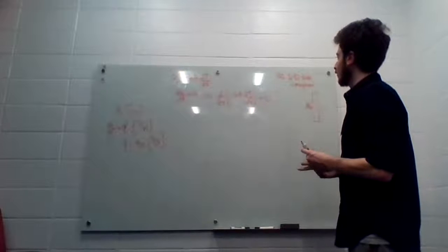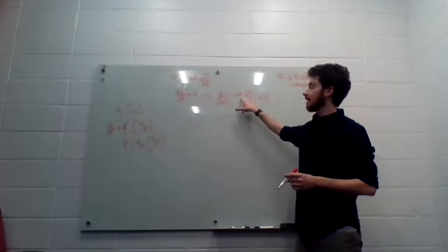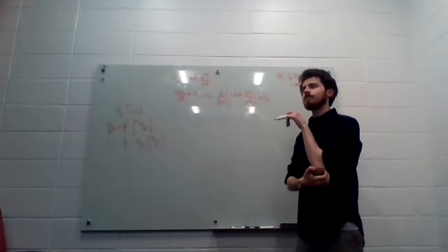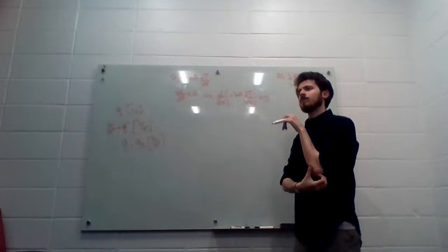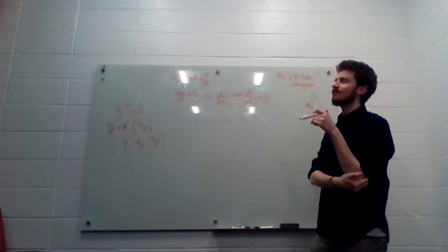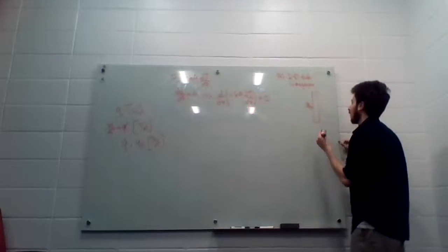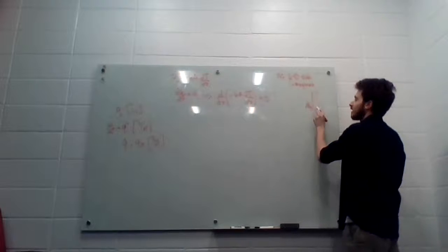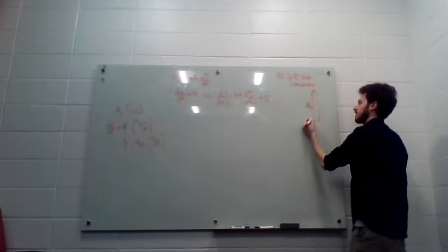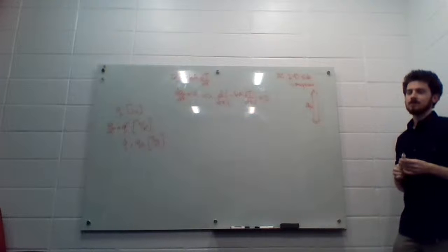Okay, so what we can do based on these two assumptions, the isotropic assumption that K doesn't change with X and the area doesn't change with X, is we can move both of these to the outside. Yes? He mentioned something about assuming that it's an infinite wall. Is that for this kind of problem, or when do we assume that? Yeah, so the reason that we assume the wall is infinite, which is a super silly assumption, is whenever you've got a finite wall, you've got corner effects. So Q right in the middle of the wall is pretty much uniform, but at the corners, at the edges, you see something different. How can we assume it's an infinite wall if we have to know the area?